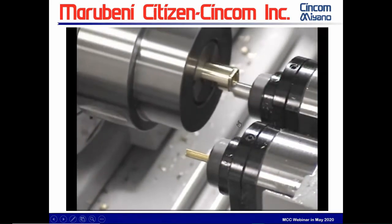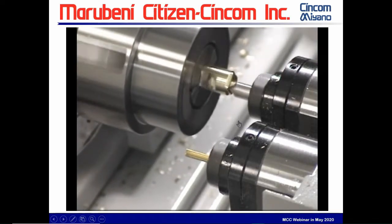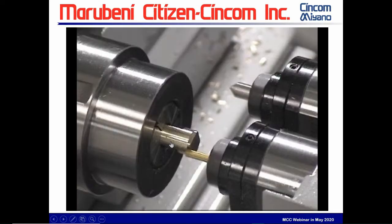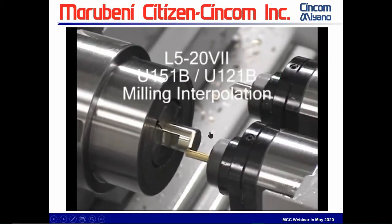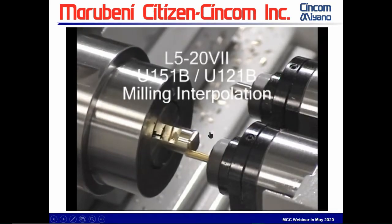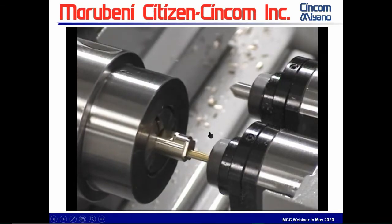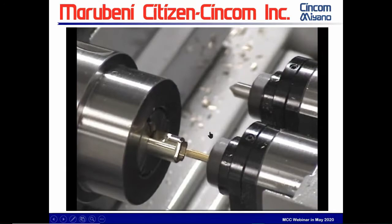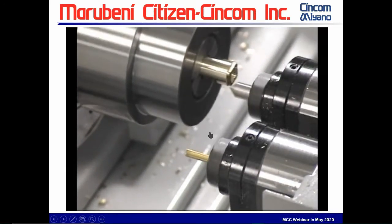Now, it also can be used, the same codes, to do the chamfering. All you would do is change the G42 value amount for that tool. Let's run it through again. You can change this, for instance, you can rough and finish if you want to with the same tool, just calling a different offset with a different R value. And you can have it rough and finish.